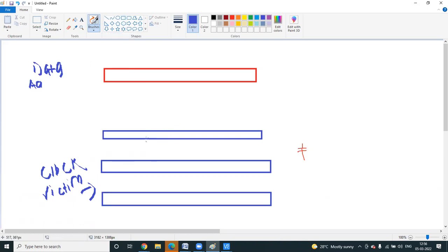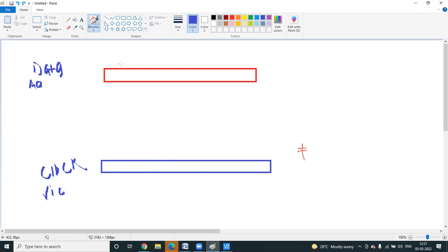The metal-to-metal capacitance will increase, so the delay will still be there. Understand or not? Yes, sir. So which one is causing the delay? The aggressor.